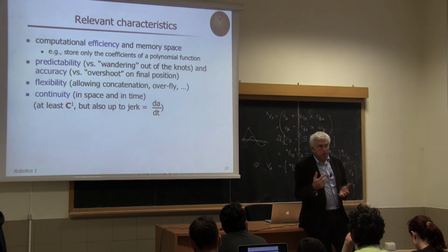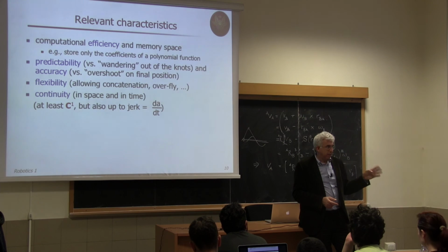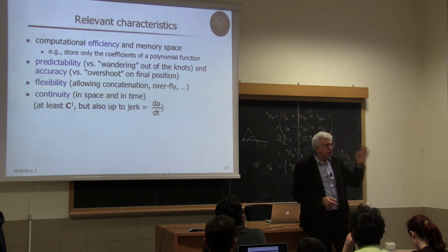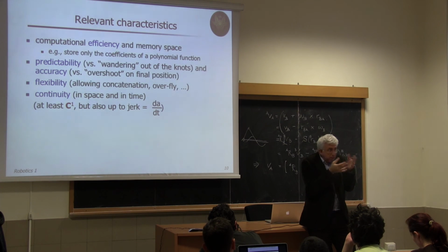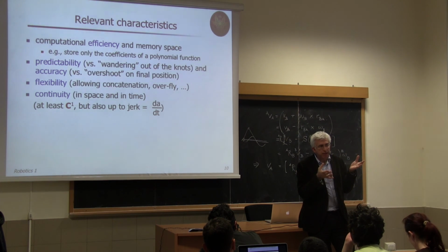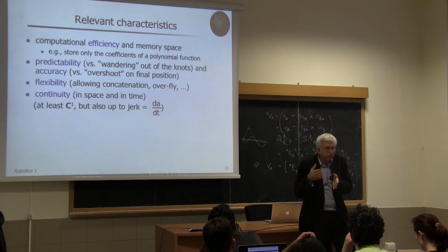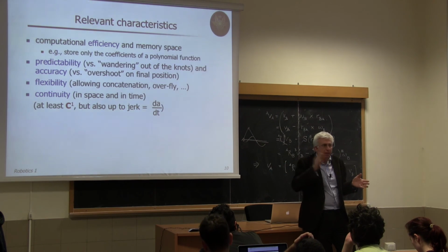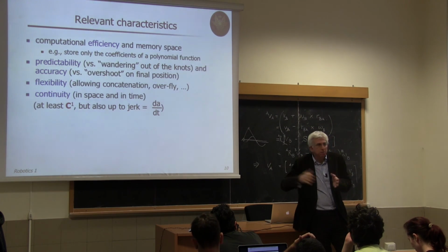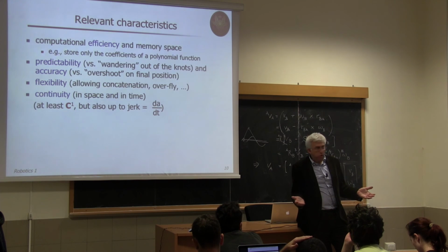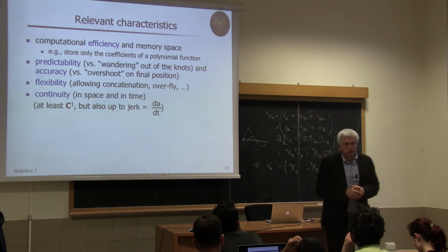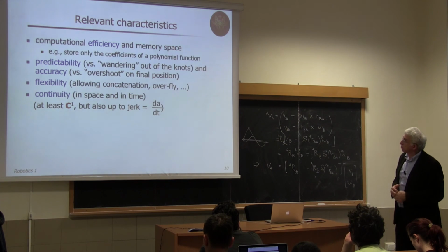The second option, by the way, when I store points in a table format, then these are already time-stamped, so every millisecond. What if I need some reference in between? I need to do some interpolation between data in the table. While if I have the expression, the coefficients, I can evaluate this at any time, not really every millisecond. I can decide to evaluate the next point after 2 milliseconds or after half a millisecond. It's a computation that I do online. So this is another important point. Depending on the application, one is preferred to the other.